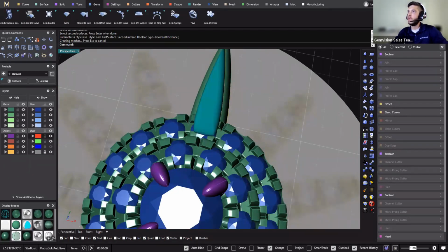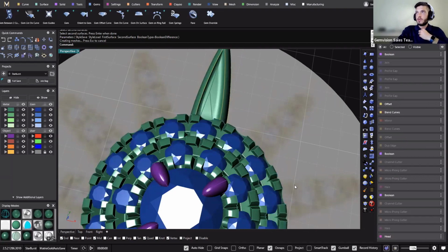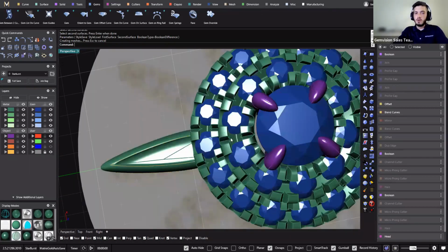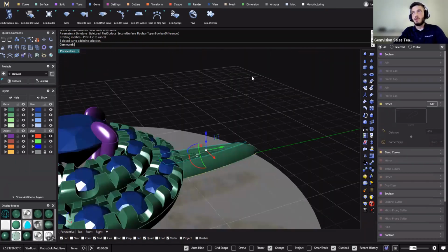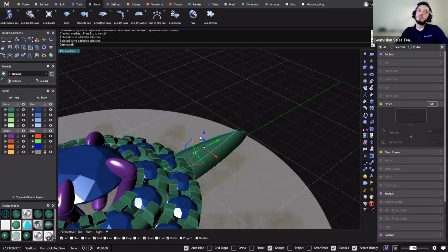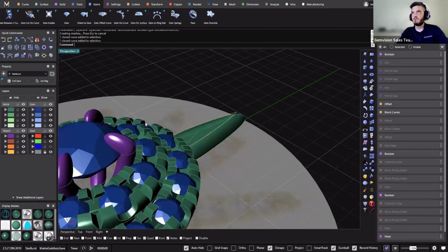Tricky, you need to be aware patch does not always hold to the edge of curves. Yes, it does not. But sometimes it's worth it to get a surface, then redo adjacent surfaces. Yeah, you can do stuff like that. Are you talking like if you have an open surface on a sweep or something? I would just try and figure out how to sweep it with closing it. Sometimes when you put patch stuff like that, it turns the geometry wonky.